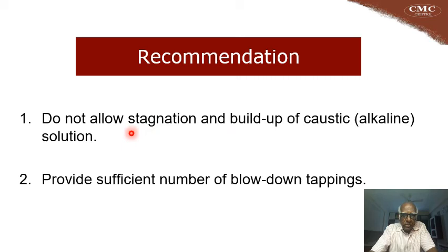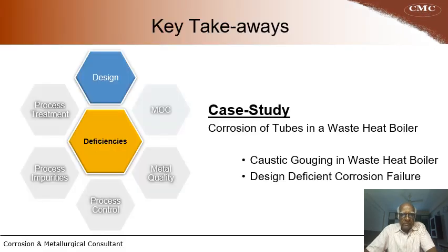So we should not allow stagnation and buildup of caustic solution within the boiler, anywhere on the boiler. In this case, it has built up at the bottommost. That is why the tubes failed in the bottommost position. So in that position, we should provide a sufficient number of blowdown tappings. So this is the recommendation for this failure.